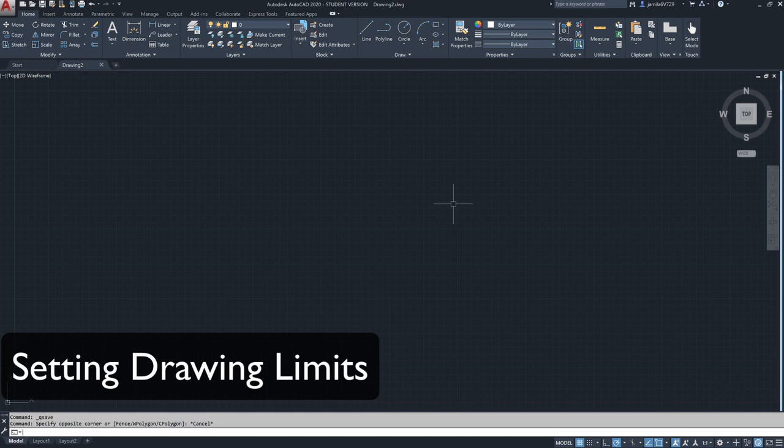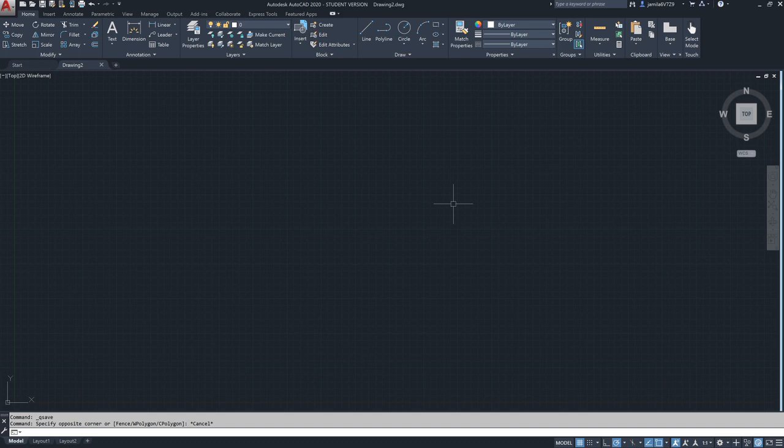In AutoCAD, we make our drawings at a scale of 1:1, which means we are drawing to the actual scale of the project. For example, a square plate of 10 mm by 10 mm will be exactly that size in AutoCAD as well. But the drawing area can make the 10 mm by 10 mm square very big or small, depending on the zoom state of the screen. If your drawing is zoomed in, the square may appear bigger, and if it's zoomed out, the drawing may appear tiny.